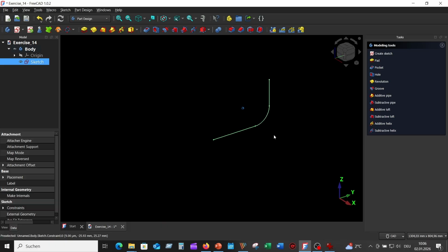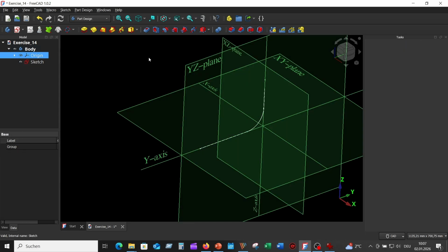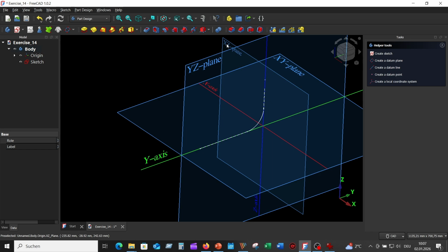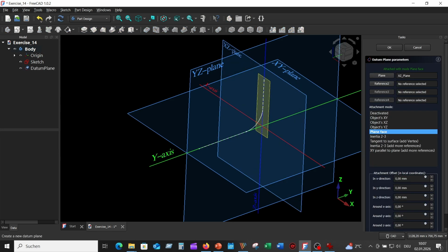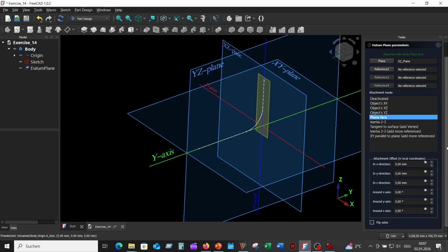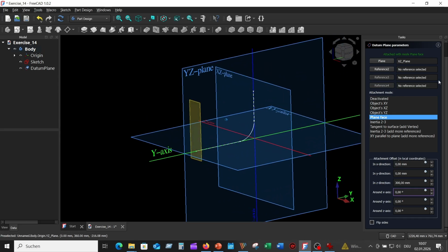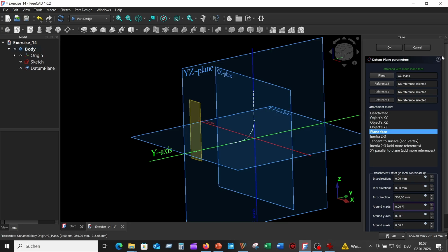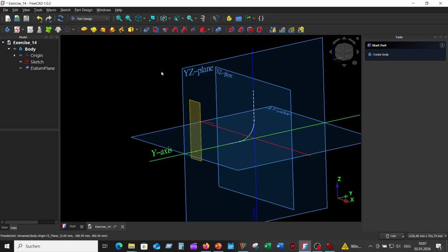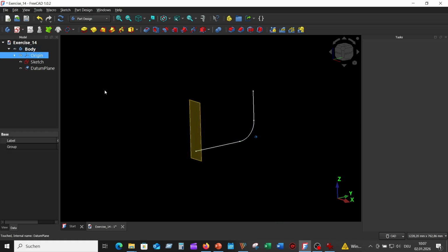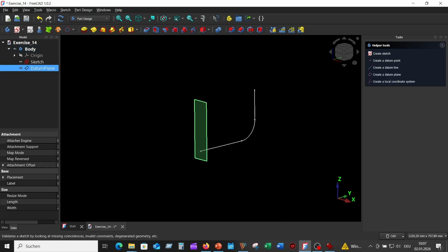Now we create the circular profile at the end of the curve. First, we need to create the plane at the end of the center curve. Select the plane and activate the Sketch tool.